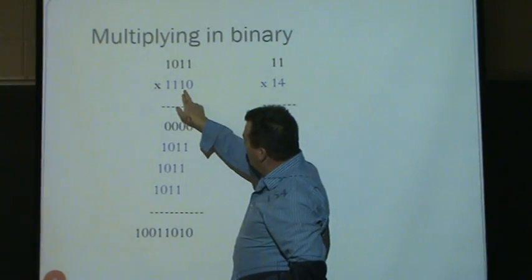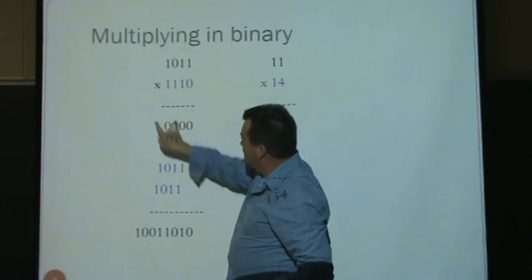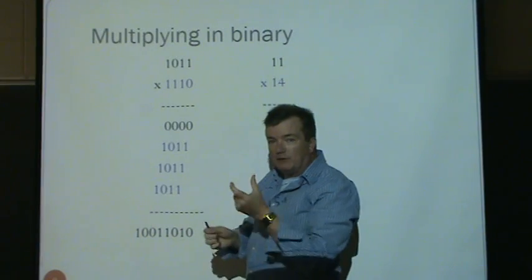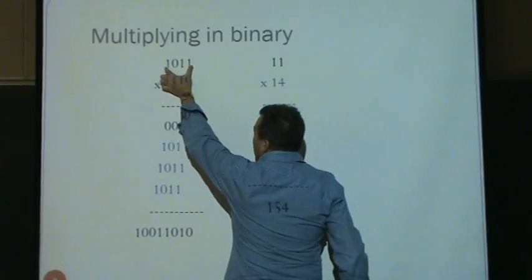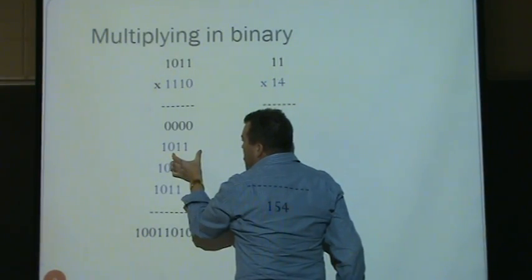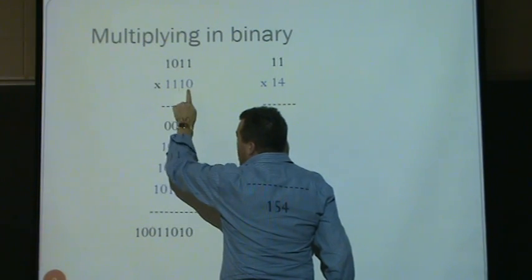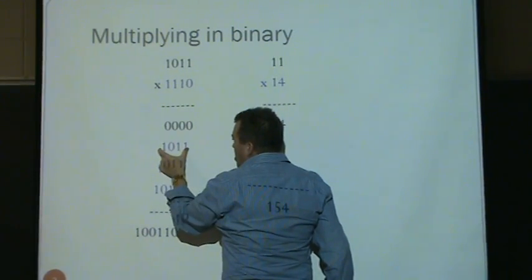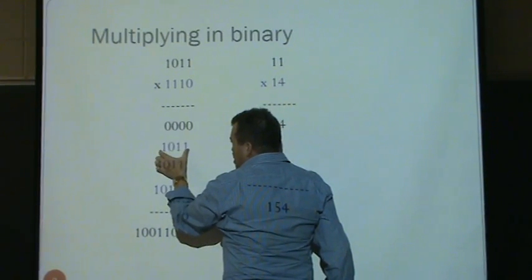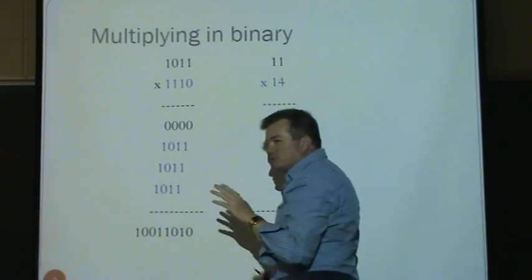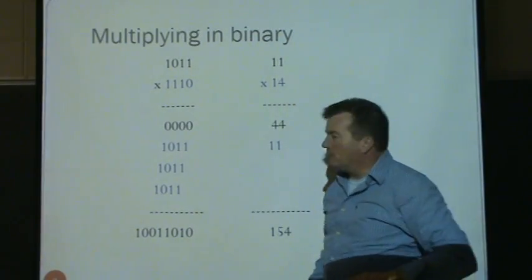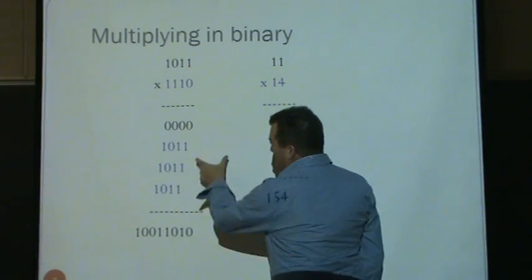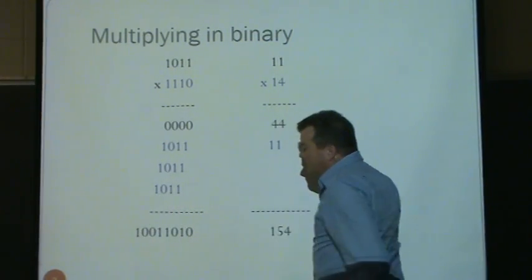And if we're doing a 1, we don't actually do any multiplication, we just copy the number. So if we had a register that contained these 4 bits, we could just keep sliding it. Every time we slide, we AND it with this bit, and if it's a 1, we add the previous number to this number, and if it's a 0, we just put it to an AND gate and it'll 0 it out. We don't even have to add it. So this operation can actually be done somewhat quickly.